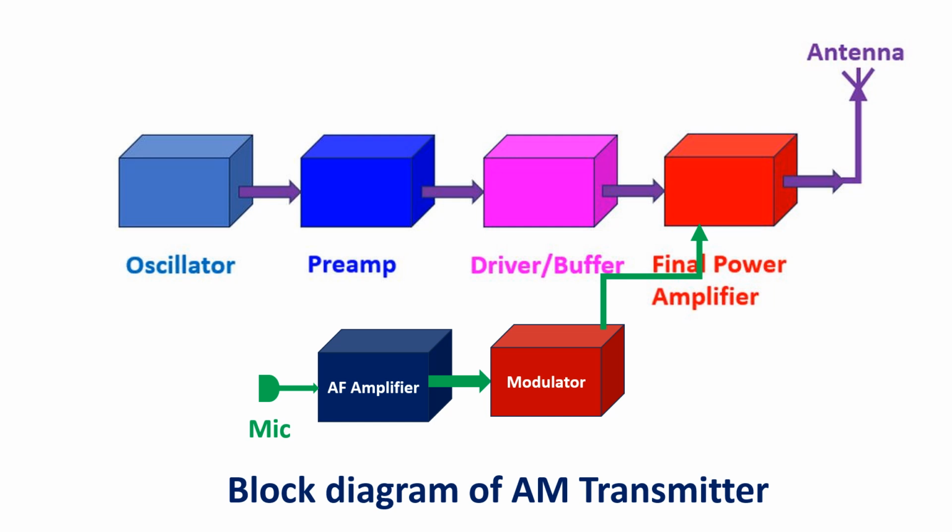Next level of sophistication in a transmitter is adding a modulator for voice transmissions. Voice signals from the microphone will be amplified by an audio amplifier and used to vary the amplitude of the carrier wave generated by the oscillator and amplified by the power amplifier. This process is known as modulation, and the simplest form is amplitude modulation or AM. In VU2VWN QRP, TBA810 integrated circuit was used as the audio amplifier for the modulator.